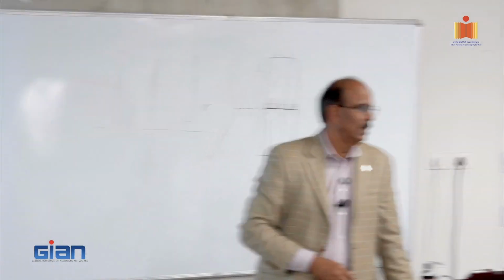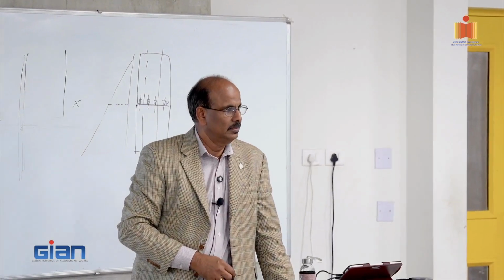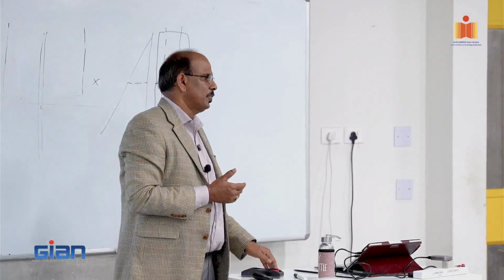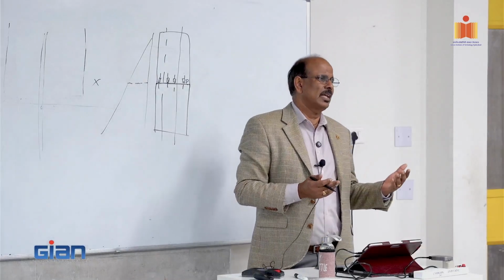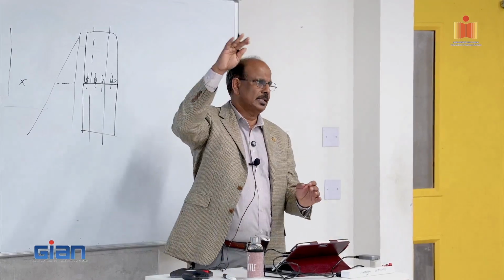Go ahead. After an earthquake, there's a pre-stress loss. Do we replace tension in the tendons? Yeah, so if you lose pre-stressing, you literally have to replace the tendon because you cannot stretch it more and try to get more out of it, because you're already in the inelastic path.